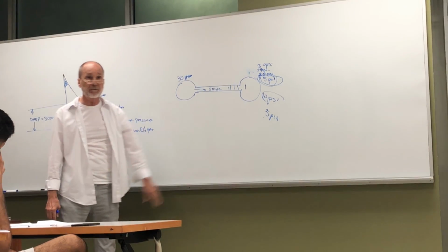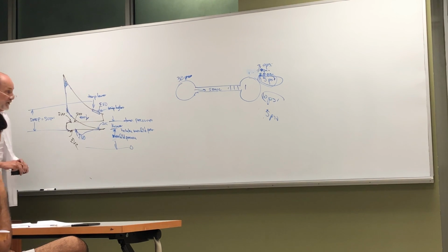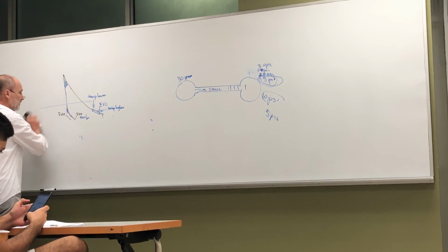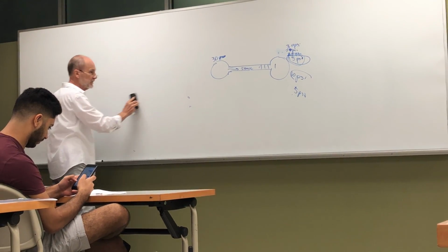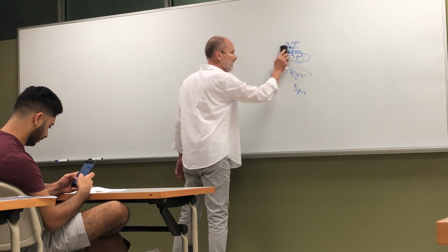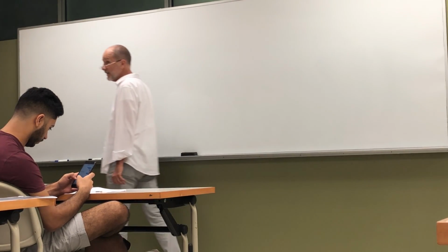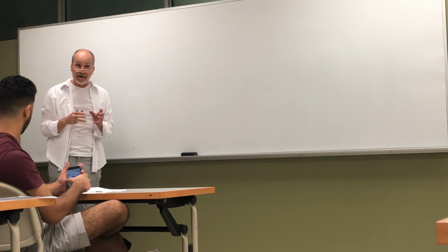Effect to determine what the maximum RPM is available in an engine. We can do a Mach index number calculation and determine that. And what that is determining is the average speed of the gases as they rush past the valve into the cylinder. And when that average speed reaches about Mach 0.5, the peak speed is reaching about Mach 1, and trying to